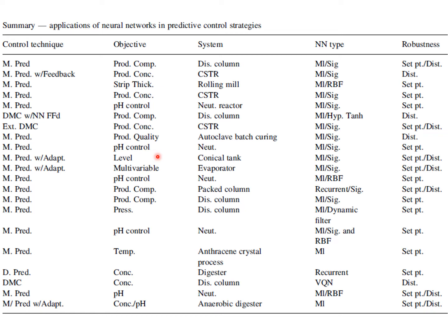So now there's more work on this in MPC, mainly using the neural network as the model within the MPC system. This is also a common usage for neural networks nowadays, using neural network models in MPC. MPC has different types of models, and this is one of them where you can use AI for some of the models of systems that are very difficult to model using the normal first principle.